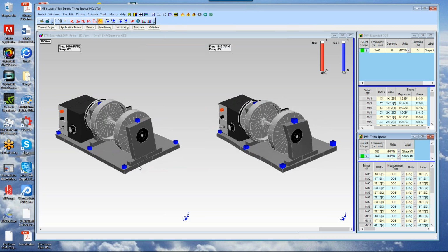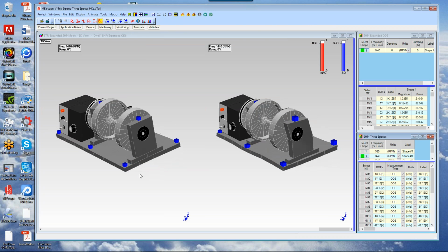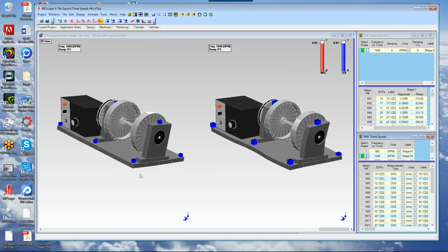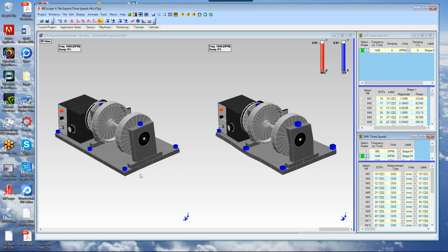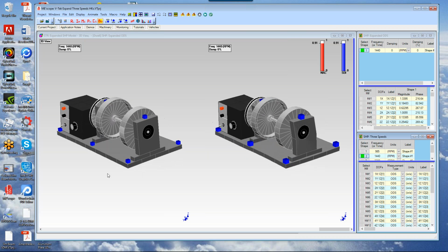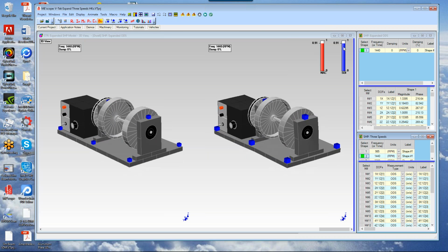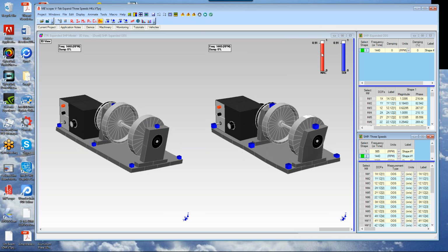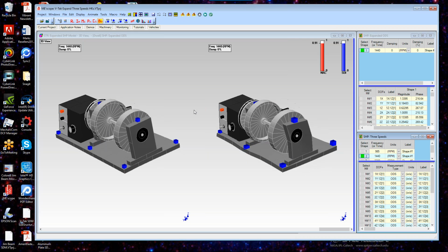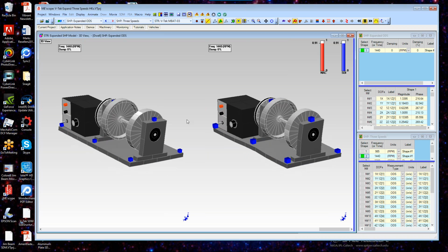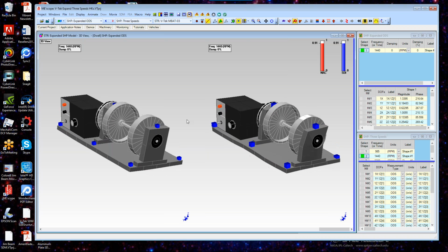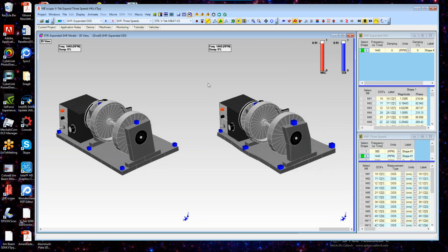The data on the left is the curve fit of 10 of the modes of the base plate and bearing blocks to the ODS data. A much cleaner animation, and it's 91% the same as the original data. So that's a pretty good curve fit. That's showing us that the 10 modes there are matching up well.